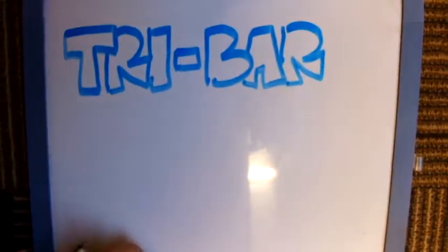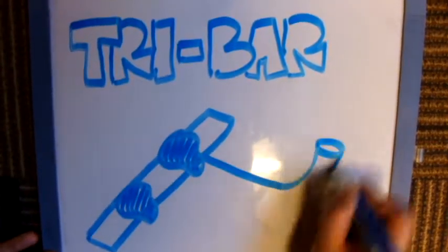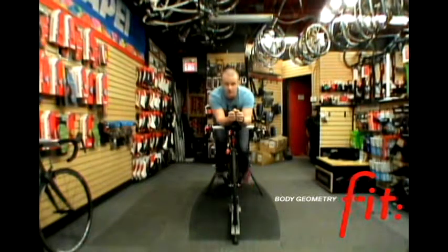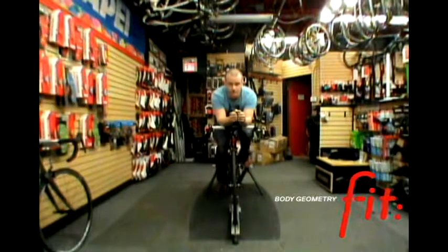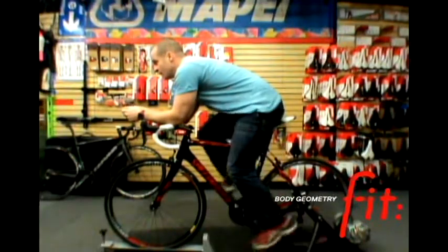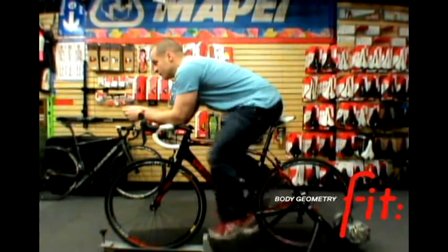The tri-bars, also known as aero bars, are commonly used during time trial races, where forearms are placed at the center of the front handles in a triangular position. This reduces air resistance dramatically, as the cyclist is also stooped down and leaned forward. The pointed edge of the triangular shape created by the hands of the cyclist causes a decreased rate of collisions at a higher angle of incidence. Therefore, less energy is lost between the object and the fluid.